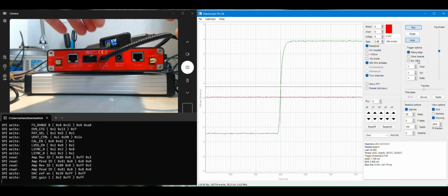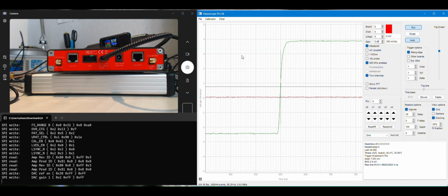Okay, so we've got the external trigger over here on the left. You can see it says 2.5 volts, 50 ohms. So that's the external trigger in. We can turn that on, and we won't be triggering, right? If I put it in normal mode, we're getting no triggers because there's nothing connected. So I would have to connect up a cable to that.